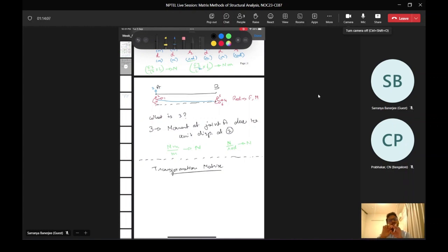You just have a single beam element, horizontal, and then you include the different fixed end moments and transverse loadings on the beams, and you get good insight into how your beam reacts. Truss elements only have tension or compression, elongation or compression.